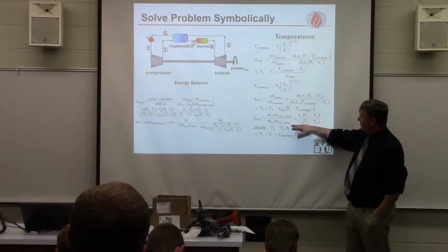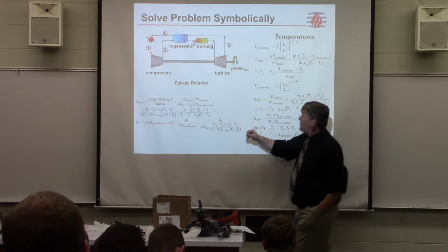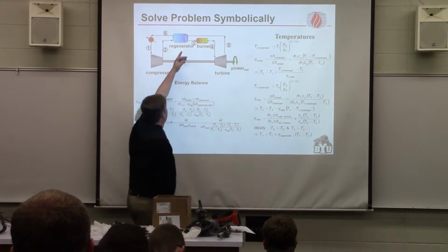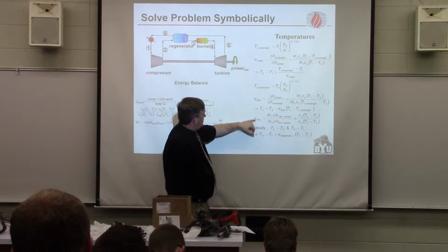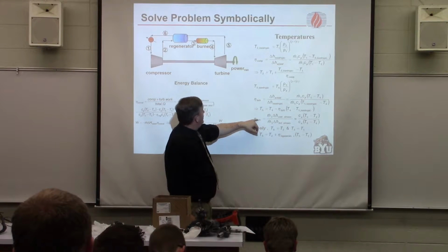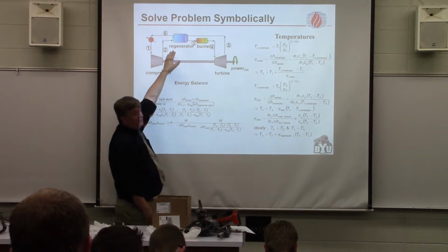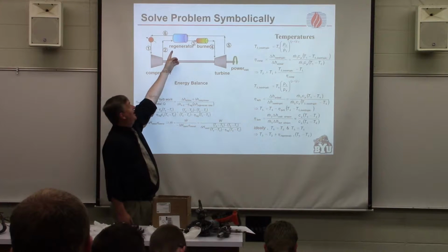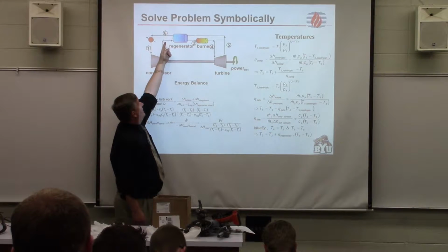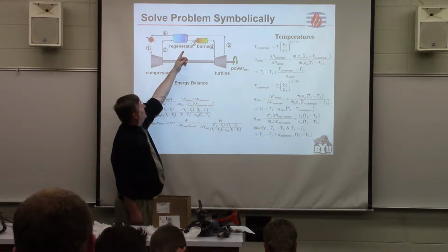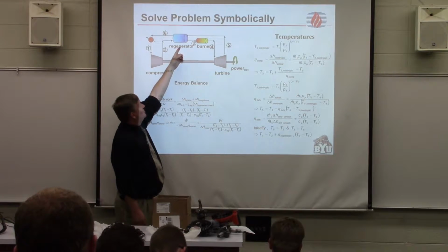The turbine efficiency is going to approximately be equal to this. Ideally, T6 should be equal to T2. That is, if this is a perfect heat exchanger, this efficiency should not be turbine, that should be regenerator efficiency. The subscript is wrong there. In the regenerator, if I had a perfect heat exchanger, then that outlet temperature would be the same in the counter-current heat exchanger as this inlet temperature and vice versa, right?